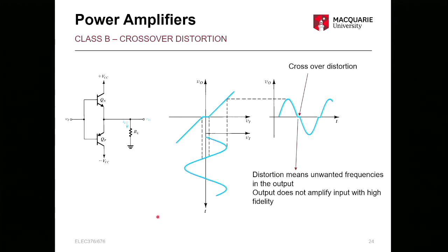So it would give you unwanted frequencies in the output. Okay, so you're going to have harmonic issues as well from this sudden change around there, and basically your output does not amplify the input with high fidelity. Okay, so any small voltages are basically just lost.